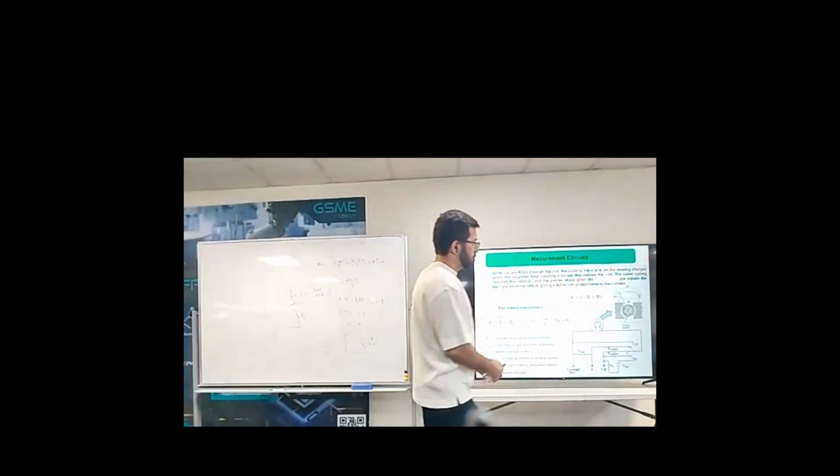But when you want to measure voltage, we have different ranges of voltage, depending on how much voltage you want to measure. You should switch between these resistors. These values are usually big numbers. And for measuring resistance, we should change the selector to this port. There is an internal battery which comes through an internal resistor, and you connect your resistor here between these two.